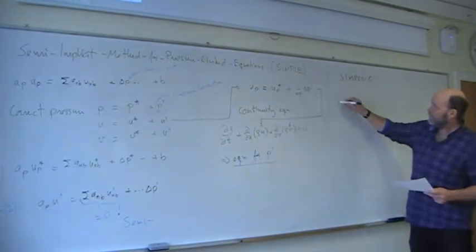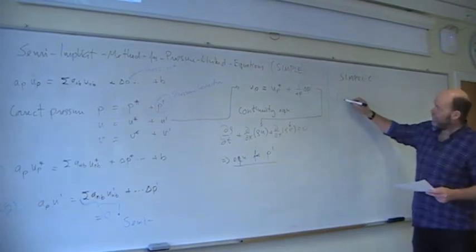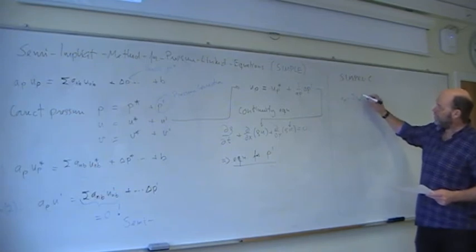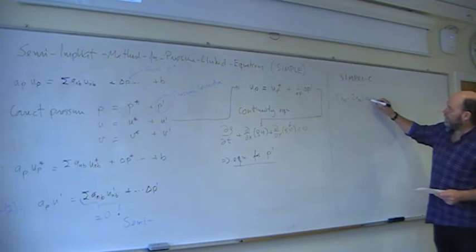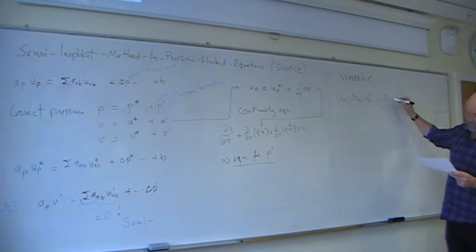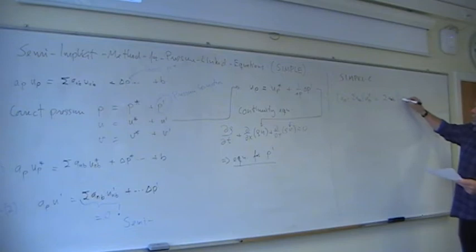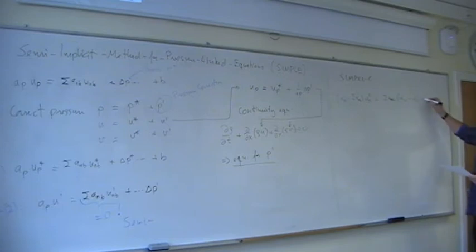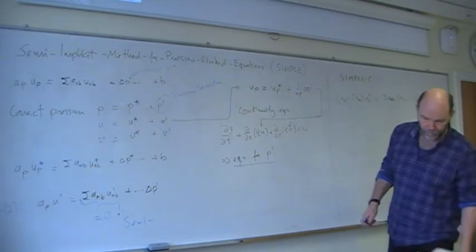You rewrite it a little bit. So you have the coefficient here, AP minus the sum of all the neighbor coefficients only, multiplied with the UP correction, equal, and then here you will now write the sum of all the neighbor coefficients, and here you will now have the difference between all the neighbor velocity corrections minus the one we are seeking, and then delta P, and maybe some coefficients there as well.